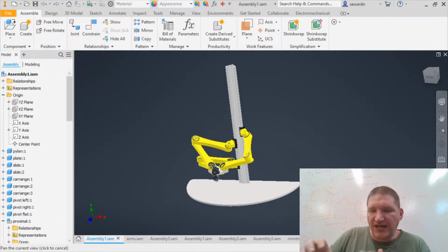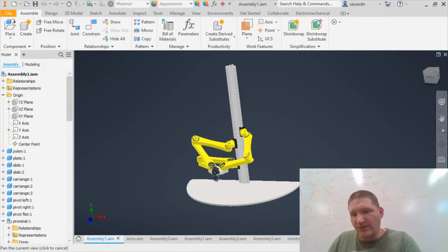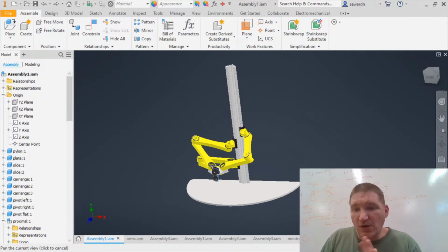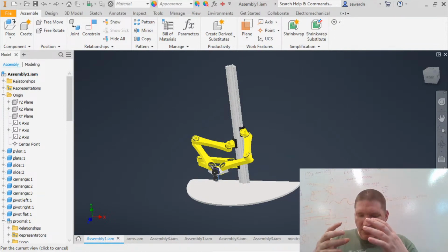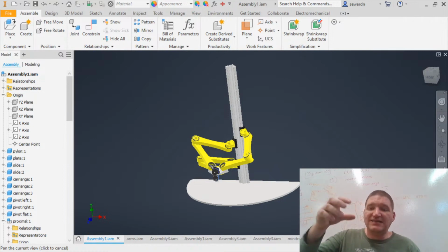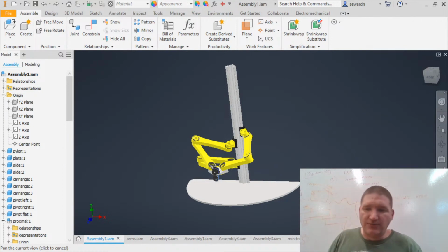If you had a servo drive, you could make a cobot where you could interact with it and push on it, and it could move out of the way and then move back. There are some really cool things you could do if you had feedback. But the most useful feedback would actually be on the effector, to know where the effector is. And as far as I know, there are not really good solutions for finding that out cheaply to the precision that we need. So basically what we all do whenever we build 3D printers is build it rigid, tell the steppers where to go, and hope for the best.